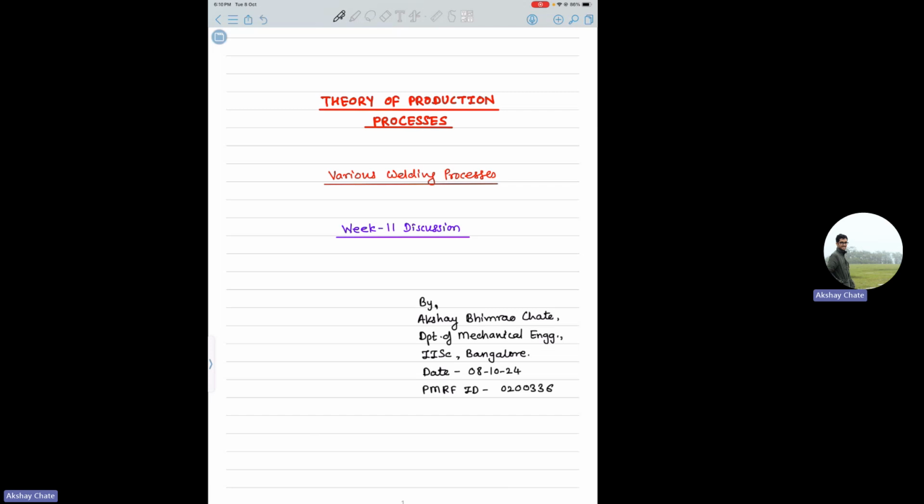It's just that you have to be careful what type of method or temperatures you need to achieve, and what type of cooling rates, because post welding, with various cooling rates, the grain structure that you finally obtain in your welded product will change. That includes the weld bead as well as the other parts, depending on the heat affected zone.